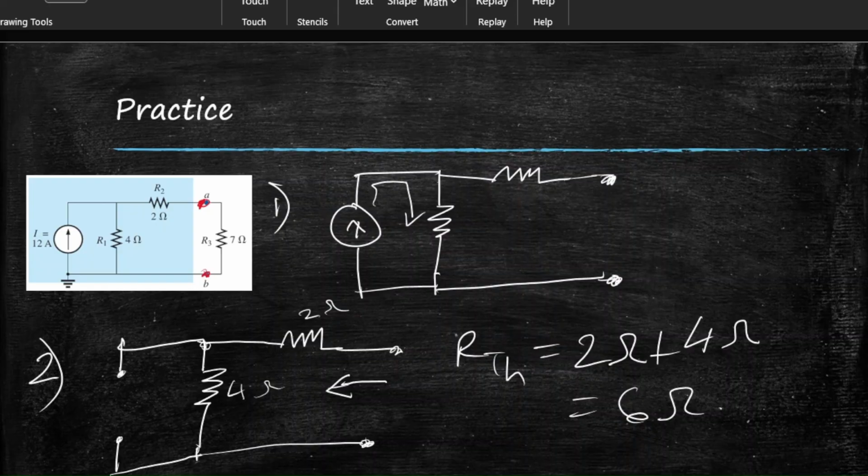When we have the circuit here, there's an open circuit, so no current is flowing through here, right? No current. Also no current flowing through this one. So the last resistor we have here is our 4 ohms. There is current flowing through this, so the voltage across it will be the Thevenin's voltage, ETH. To find that, we simply use ETH = V = IR, Ohm's law.